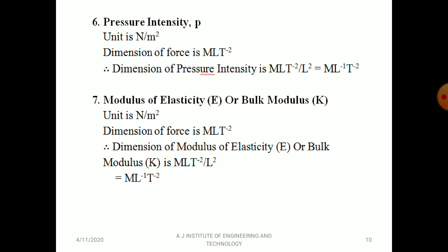Next, modulus of elasticity, that is the Young's modulus, represented by capital letter E, or bulk modulus, that is represented by capital letter K. Unit is the same as pressure intensity, Newton per meter square. So dimension of force is M L T to the power minus 2.